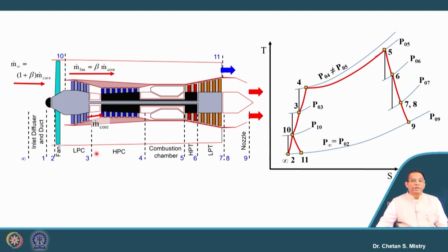Here no information is given. So, since we have an LP turbine and an HP turbine, we have a two spool configuration. Since we have discussed this cycle where my LP compressor and fan are rotated by the LP turbine, that is the reason we are putting this as a line diagram. But you need to be very careful whether it is mentioned or not. If it is not mentioned, then you can move forward with whatever you want to assume. So, be careful. Okay. And this is representing our TS diagram.